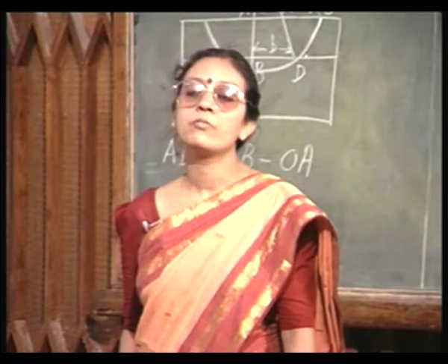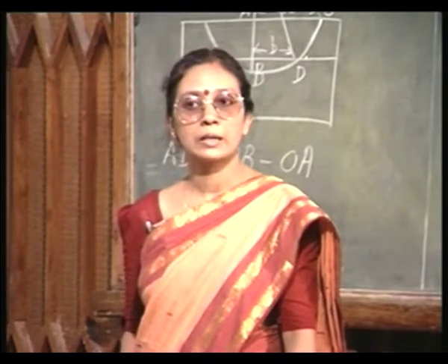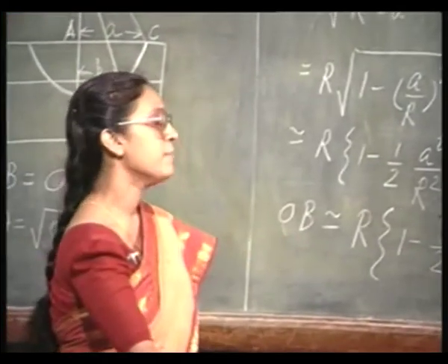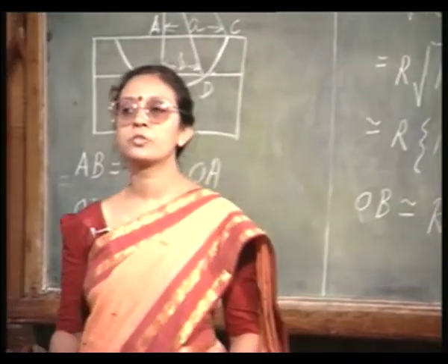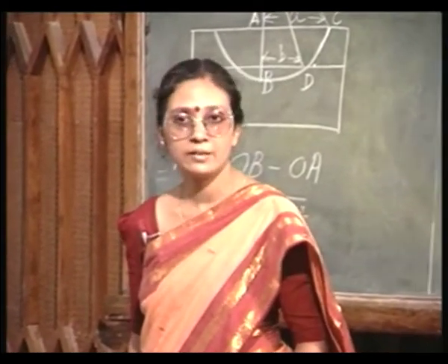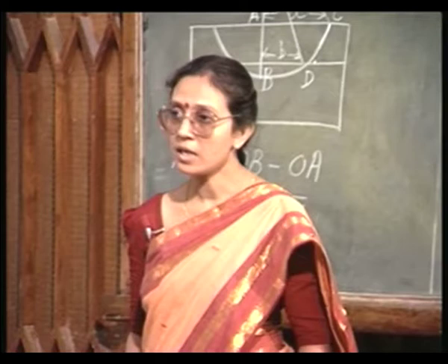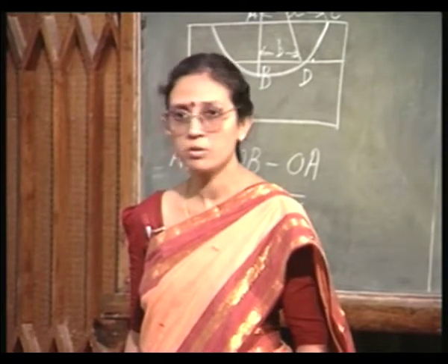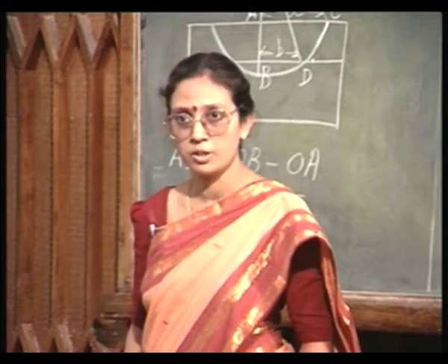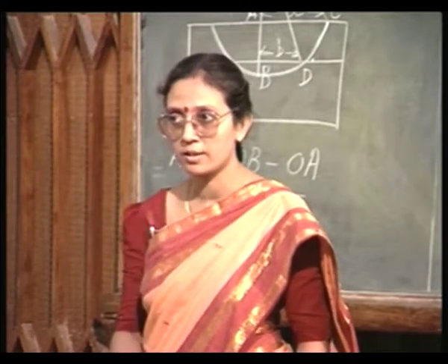So, you have no option but to look at the current voltage characteristics. Now, let us say you have a doped region of a particular length, a particular width, and you also know the junction depth, therefore, it is of a particular thickness. I have already finished measuring the junction depth by using one of these three techniques.